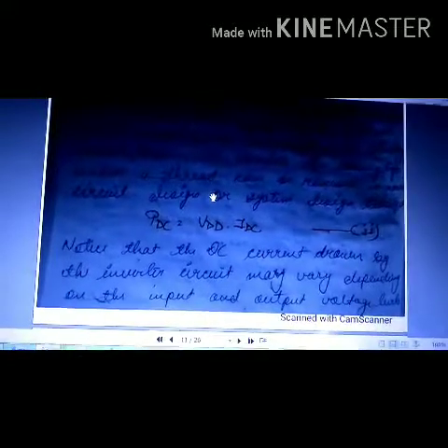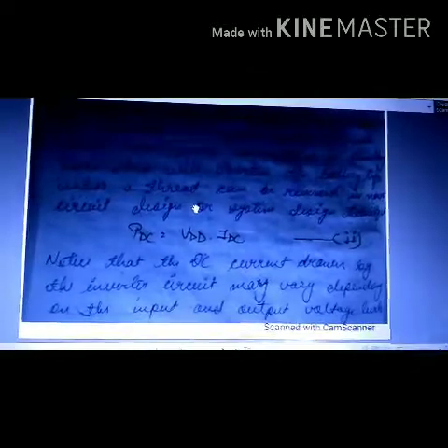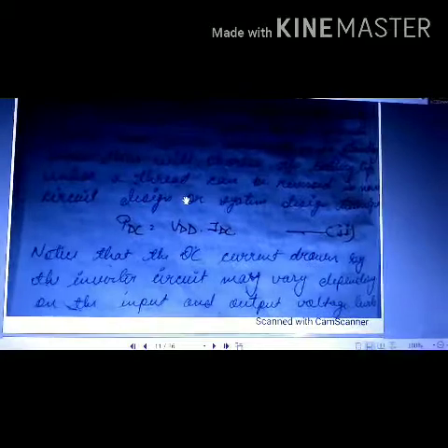If the circuit is switching its characteristics and the voltage is somewhere between VIL and VIH, then it will consume more current. Whereas if the circuit is stable at logic 1 or at logic 0, normally drain current does not flow. So at this time power consumption will be very less, because current flow is less and only minority current will be flowing in this condition. So depending upon the current conditions as well, it depends what is the power of our circuit.